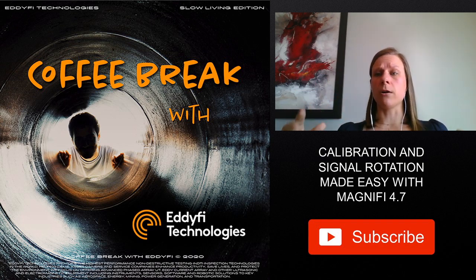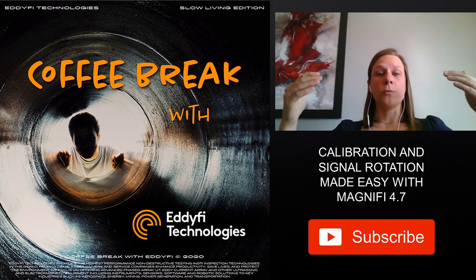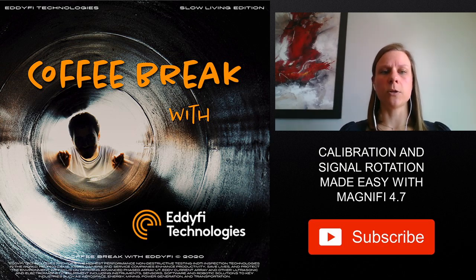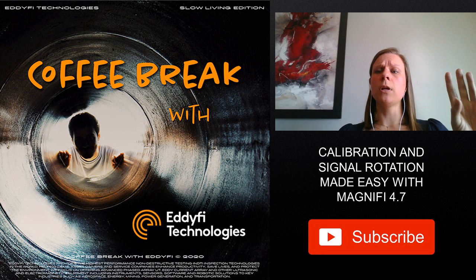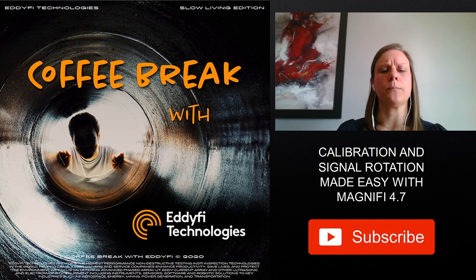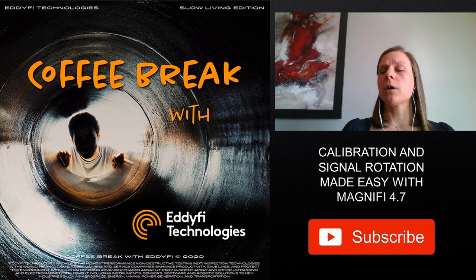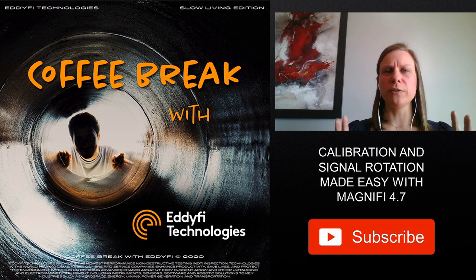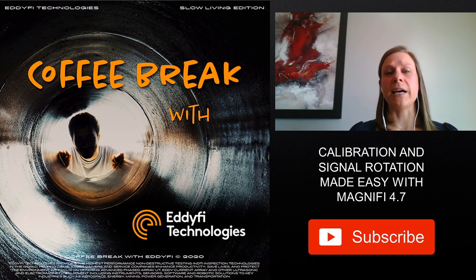Or if you're doing a job, there are hundreds of pipes. When you're going from one to the other, there might be some small variations that will affect the signal rotation, so you might want to adjust it rapidly. So that's the idea behind this tool, making it easier to do that rotation. Most commonly, and that's the example I will be using today, what we want to do is to rotate the liftoff to the horizontal. This is quite a universal reference signal that we can use to perform the rotation, so that's why I'll be using that as an example today.